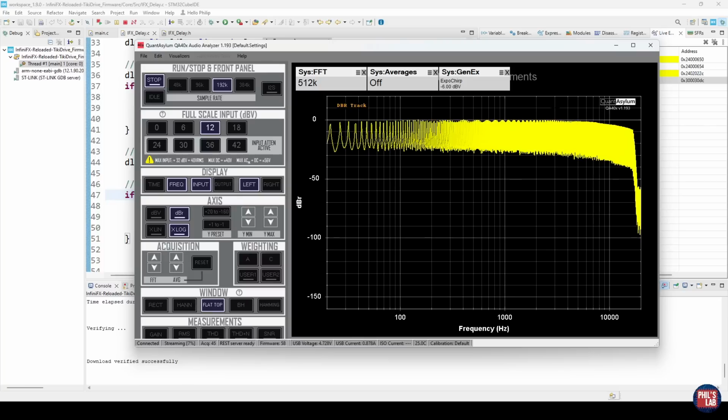But the actual frequency response is rather interesting and very reminiscent of our comb filtering structure, and we can see this particularly on the left-hand side, that we have these notches and peaks in our frequency response, which is very typical of comb filtering. This is because, due to the delay, we will get peaks and troughs from being in and out of phase at certain frequencies. We would have to increase the FFT resolution to see finer detail, but this kind of comb pattern actually continues all along this frequency response and of course changes depending on the parameters we use.